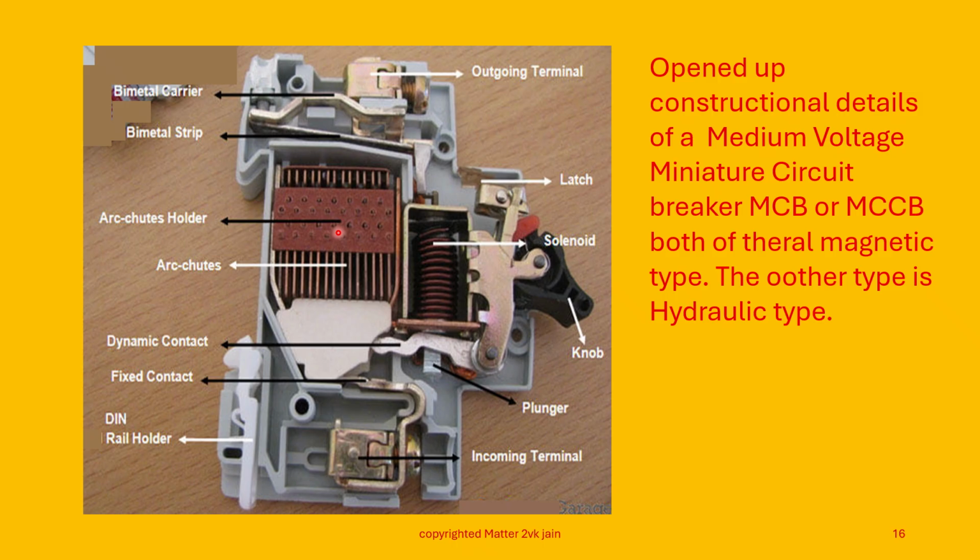the heat of that arc goes through this large arc tube in which the current travels. It takes a very lengthy space to travel, and thus the current gets thermally cooled and the circuit is broken.